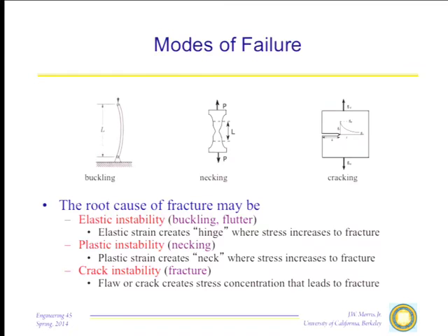And that can be such a threatening thing because you don't necessarily know the crack is there. As we'll see, there are mechanisms in which cracks can appear in the material during service. Fatigue, stress corrosion cracking. And so you can be operating something and it's operating fine, everything is great, all of a sudden it breaks. With no warning at all and under no unusual load at all. And so this is a very important kind of failure to understand.